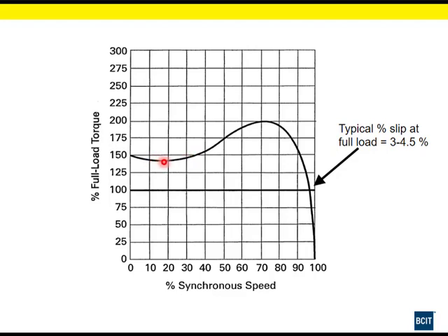And our voltage is reducing. Our induced voltage in our rotor is reducing. So as it starts to accelerate the rotor, our induced voltage is dropping, our power factor is dropping, so our power factor is dropping more than our induced voltage. So that angle of improved power factor is why we have an increase of torque at this point, all the way up to, I'd say it's 20 to 25% slip point is usually where it's at.